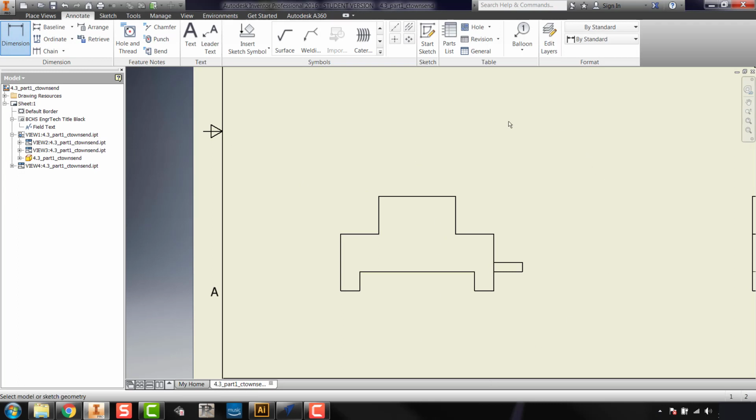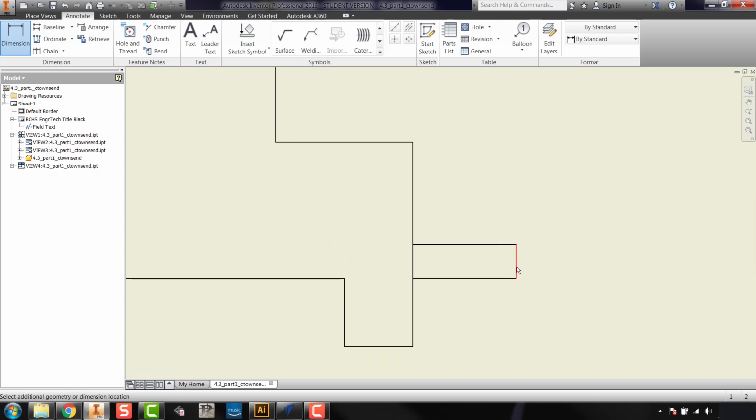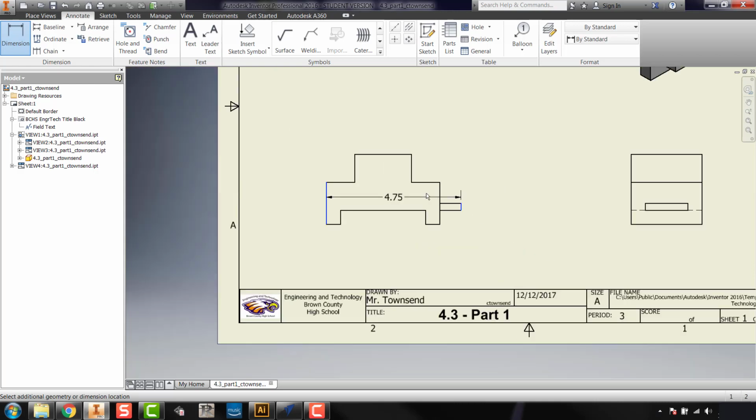and I'm going to go through and initially place my overall width dimension, which is going to be from this far left side. And you'll notice these green dots pop up. Avoid clicking those if you can. Just click there, from that edge, zoom in a bit here, to this edge. And then I'm going to drag up, and you can see that there's certain places where it snaps. Want to make sure we have enough room to add the rest of our dimensions.